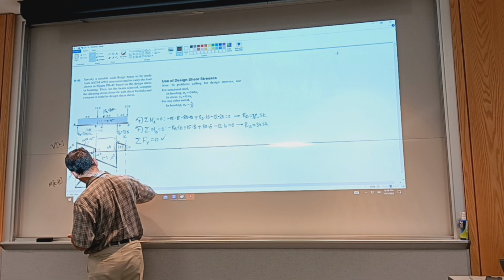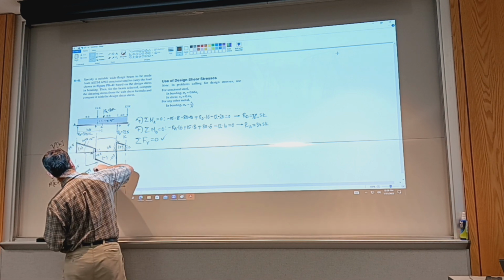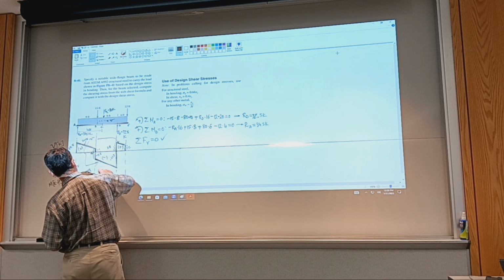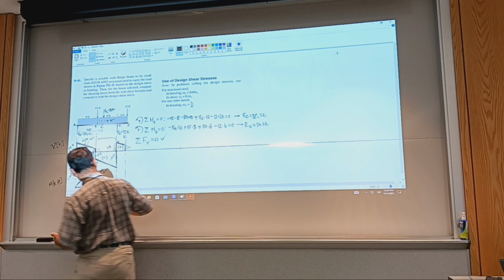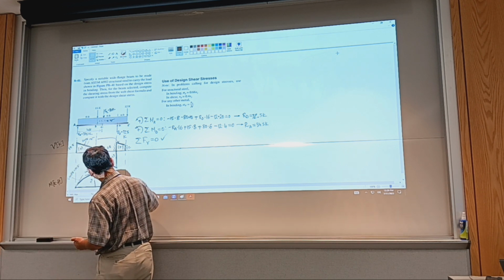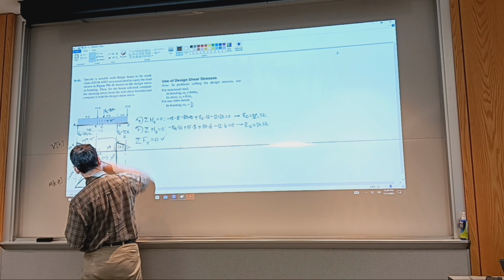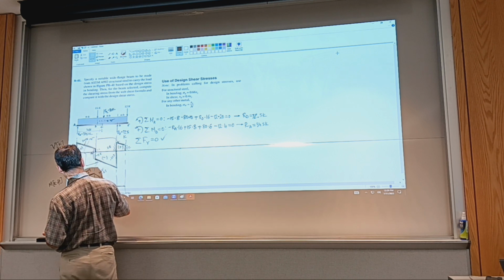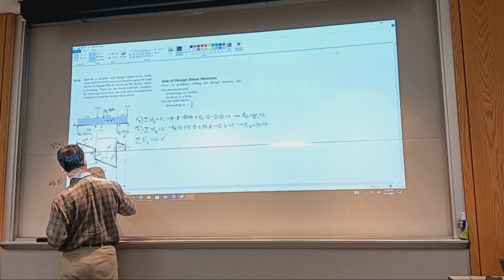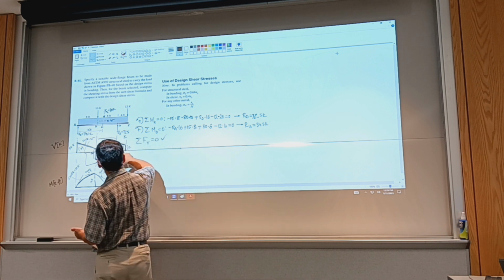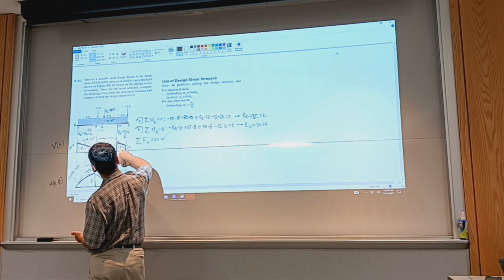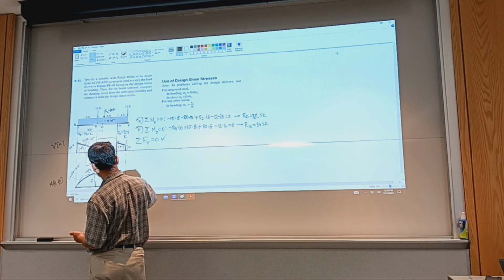Okay, if I draw the tangent, the slope is negative 12.5. In this one here, again, I drew the tangent to the moment diagram left of point D. So the slope is going to be negative 44.5. Okay. And then my moment diagram needs to close to 0, and it's a parabola again.